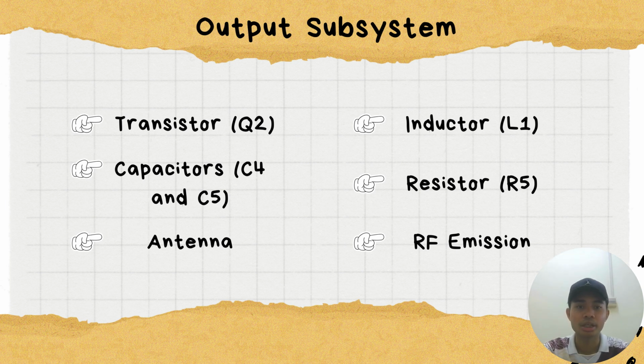Next, the antenna. The actual part that emits the energy as an electromagnetic wave into the atmosphere is the antenna. Antenna length and design are important factors that are usually selected according to the carrier frequency wavelength. The antenna is typically a quarter wavelength or a multiple of it for effective transmission. Last but not least, RF emission.